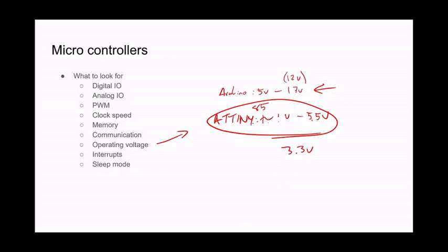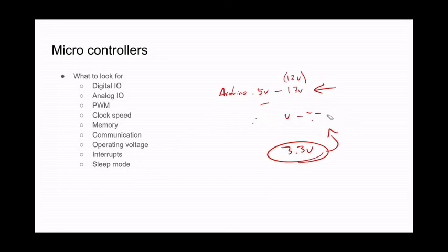Around 1 volt, we'll just put it that way. All of a sudden you can use these smaller batteries and you don't need to worry about a buck converter or a boost converter to bump it up or bump it down. You're able to have much higher efficiencies, and that's just better across the board for longevity and project duration, in essence. The next one is interrupts.